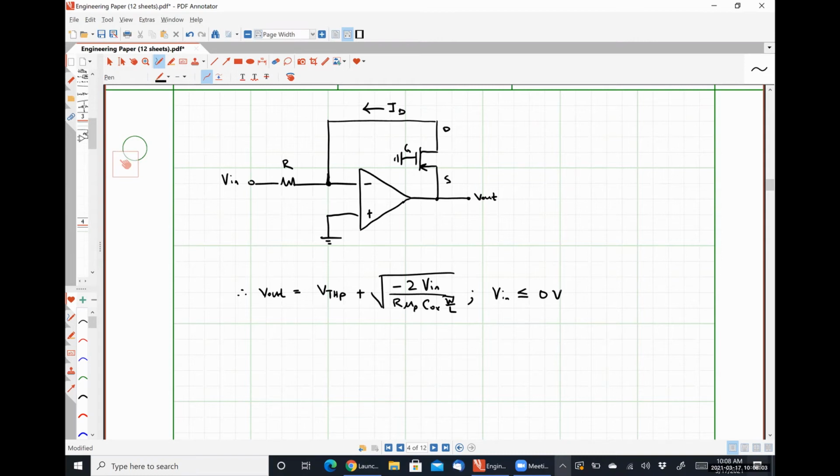So our input voltage always needs to be negative or 0. And our output voltage is VCC minus, or the negative supply voltage, when Vn is positive. So all of these transistor circuits with a transistor in the feedback loop, whenever the feedback loop breaks open because the transistor is off, this becomes an inverting comparator. This is what's going on. So.